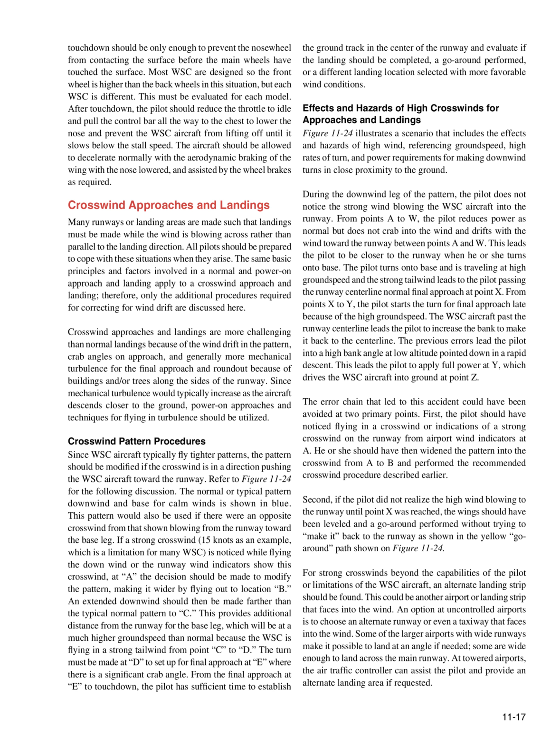Crosswind pattern procedures. Since WSC aircraft typically fly tighter patterns, the pattern should be modified if the crosswind is in a direction pushing the WSC aircraft toward the runway. Refer to Figure 11-24 for the following discussion. The normal or typical pattern downwind and base for calm winds is shown in blue. This pattern would also be used if there were an opposite crosswind from that shown blowing from the runway toward